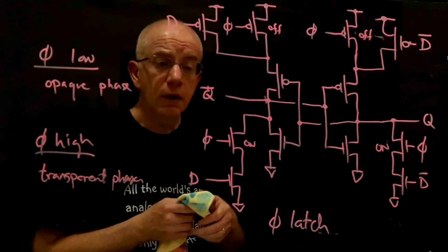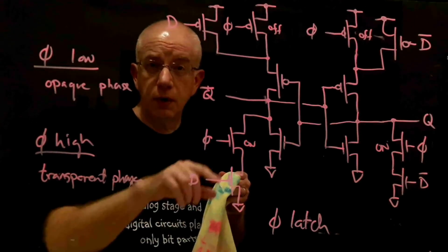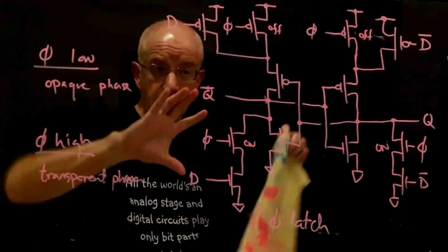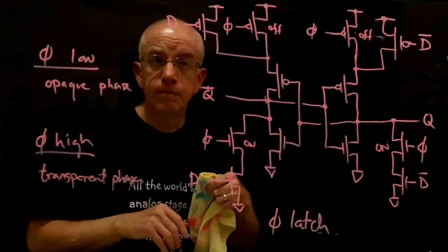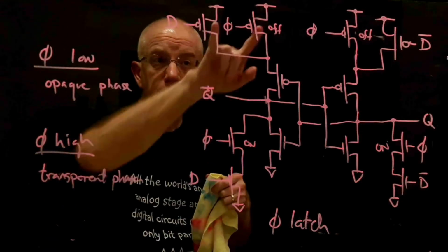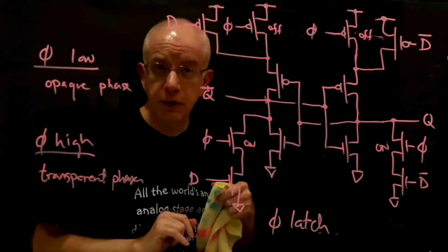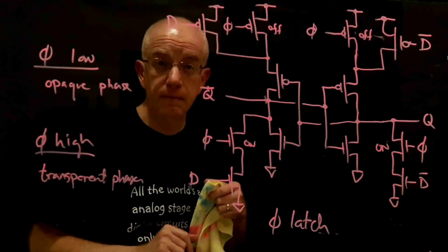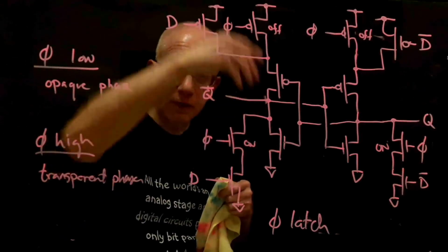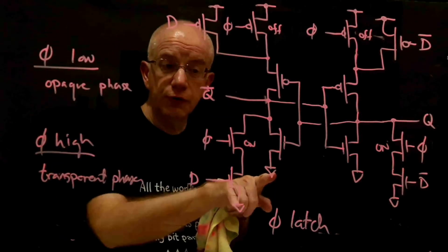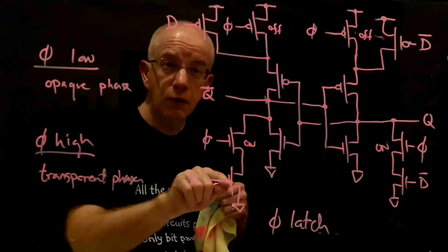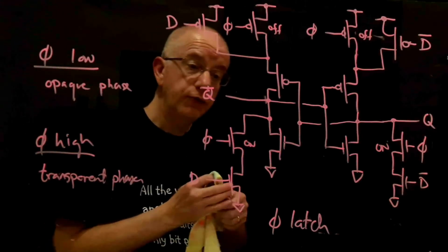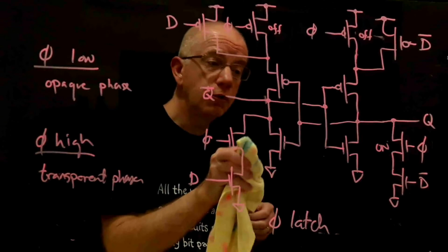Okay, so the way that you flip something upside down is you make all the NMOS transistors PMOS transistors, you make all the PMOS transistors NMOS transistors, and you literally flip the whole schematic upside down. So these points up here become ground. These two transistors become NMOS transistors down here in parallel. They'd be in series with another NMOS transistor, and that would be the pull-down network with half the gate. And then this structure would be flipped up. These 2 points would be VDD connections. You'd have 2 paths in parallel in the pull-up network. These 2 transistors would be in series in parallel with that single transistor there. Okay, and we'll draw that.